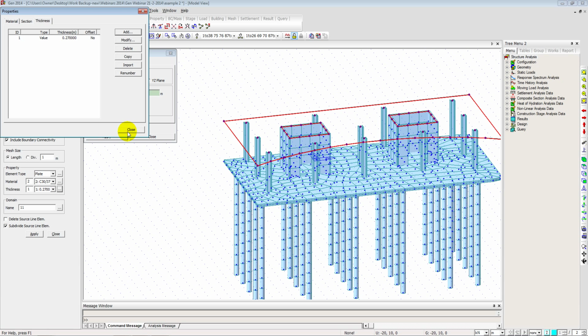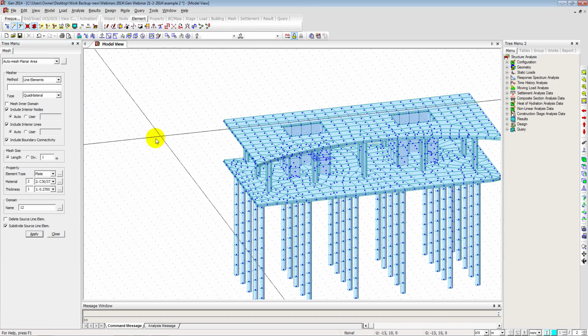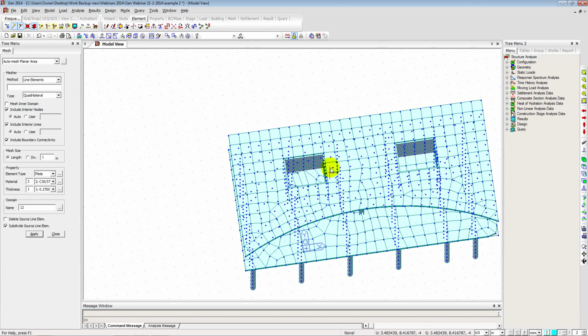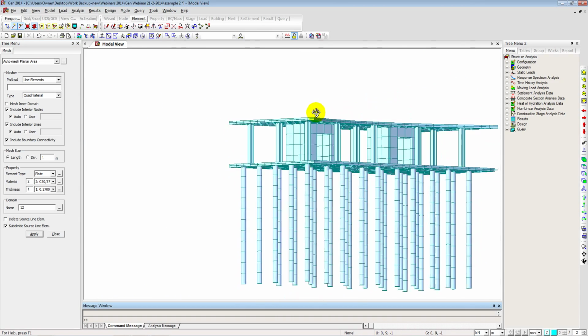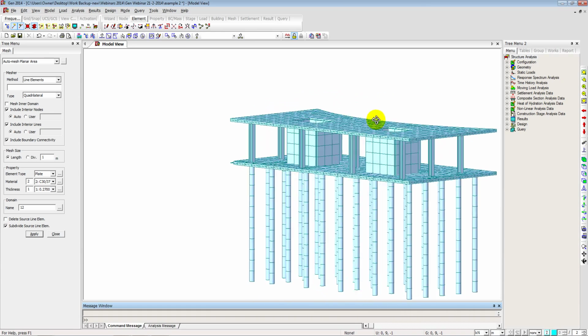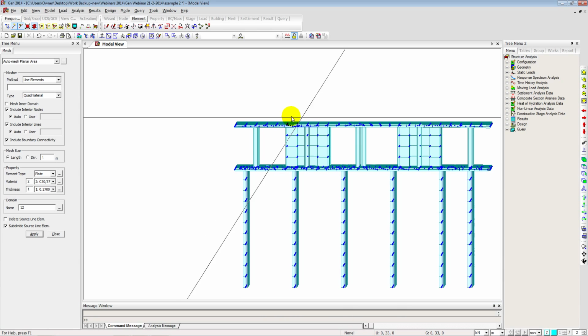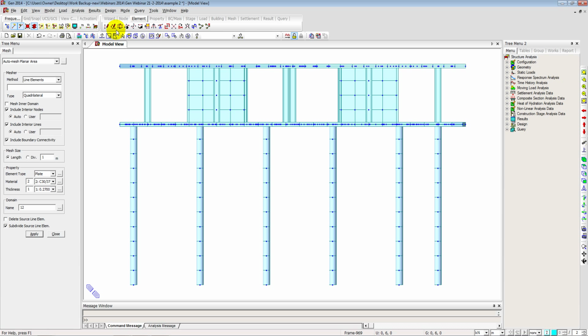That's the floor defined. So just click apply now. And they've given it the real thickness as well. So now that we've just generated the floors and we've even got the openings, we can basically use this as an outline and select the whole floor and then just multiply it over a number of different floors.